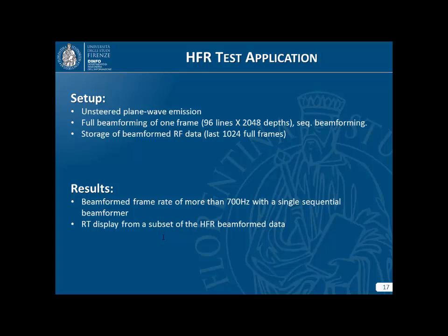And the results were that we were able to beamform up to 700 frames per second, slightly more, using one single beamformer inside the FPGA. And since we can go up to 8 beamformers, you can scale up the performances when we will have finished the test, obviously. And also, this frame rate can also be scaled up with frame dimension, as you probably know.